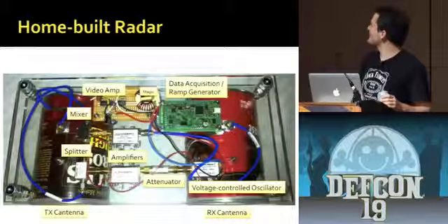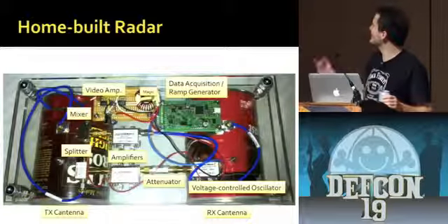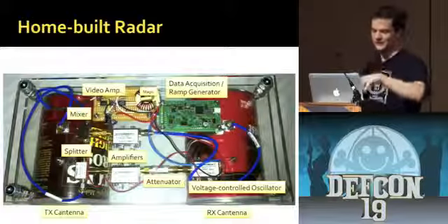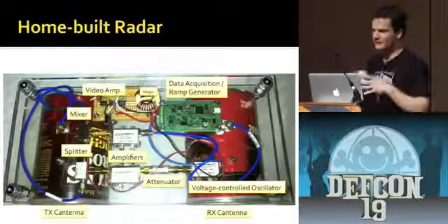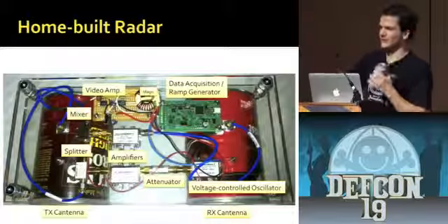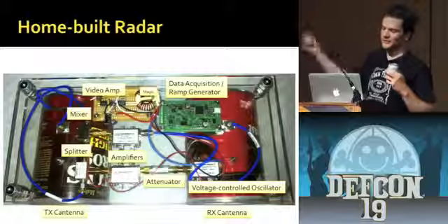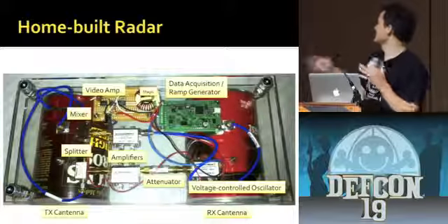Oh, so the reason that's there is because when I was trying to make this thing USB powered, I just wired it onto the power for this other stuff. Everything on here runs off of 5 volts. So I plugged the USB in, and the computer doesn't like that. It just turns off the port. The problem was the inrush current was too high, and I needed something to slow that down.